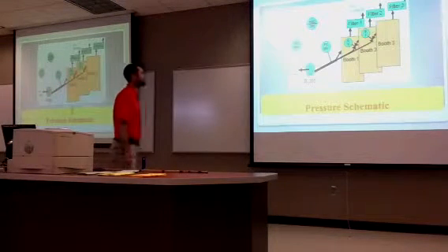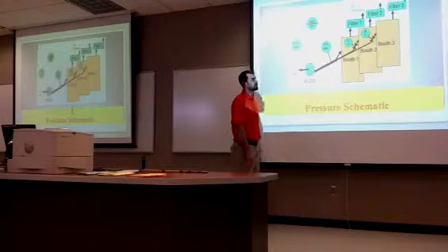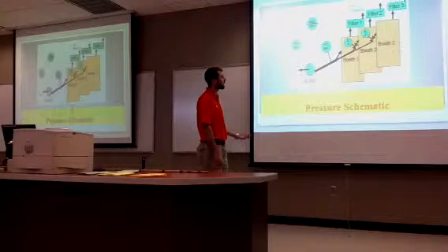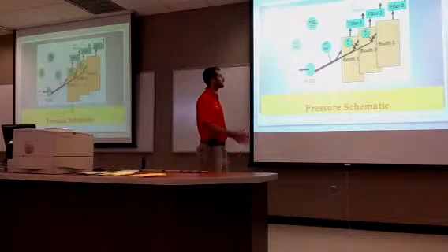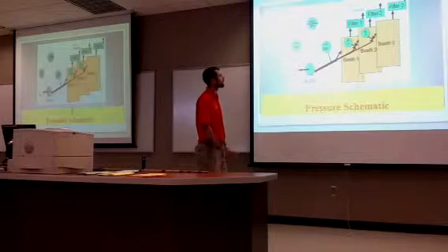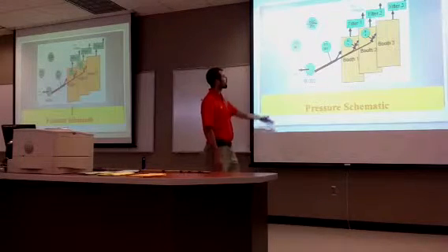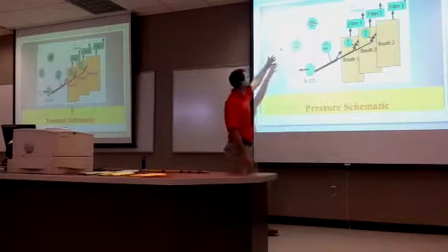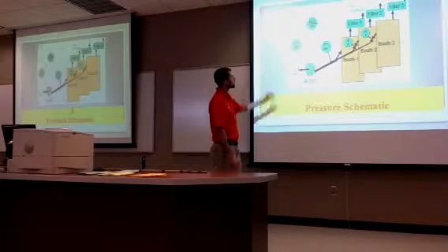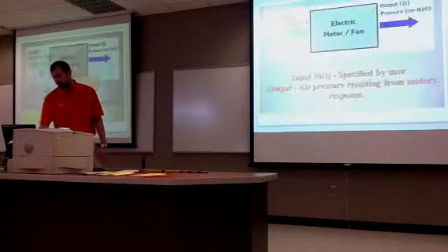This is the schematic of our system. We have an electric motor that uses a fan at the end of the output shaft, which produces air pressure to go to three different booths that are used for painting, and the air is used for filtration. We have three different filters on our system. We have a pressure sensor that relays back information of the pressure in centimeters of H2O to our computer, so we get to collect the compiled data.